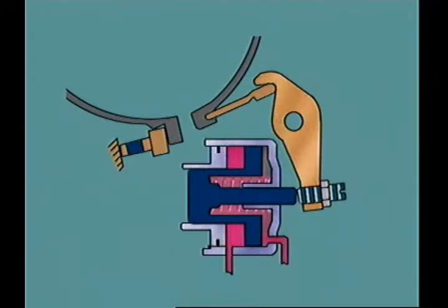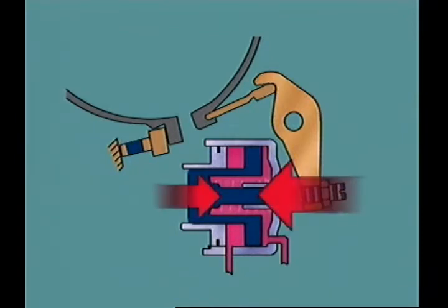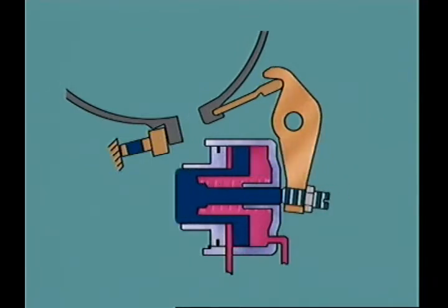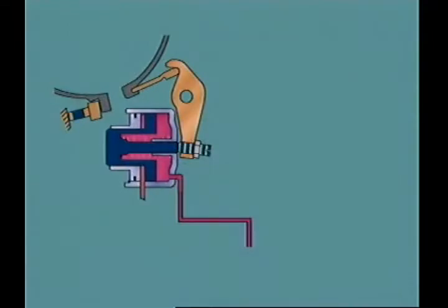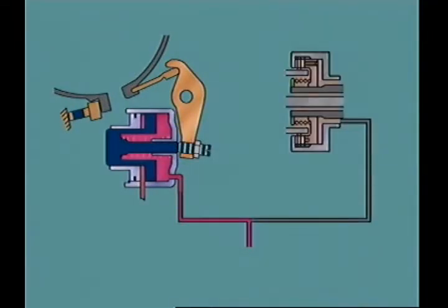When fluid at the same pressure is directed to the release side, the differential area results in a higher release force. The band can be released even while apply fluid continues to exert force on the piston. The fluid directed to the release side can be directed at the same time to a clutch piston to bring the next component into operation.